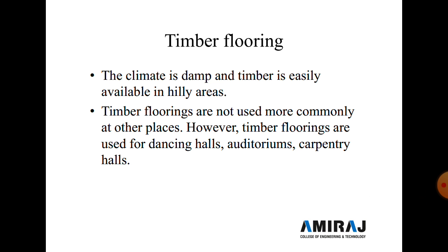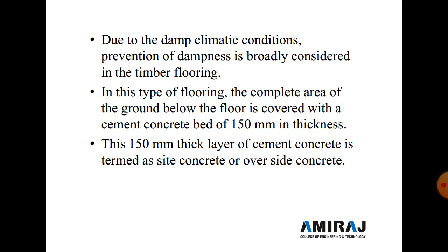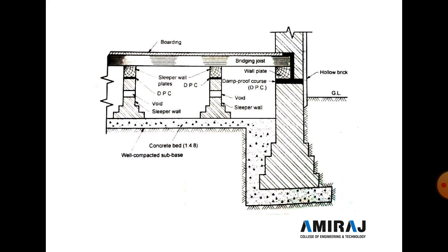auditoriums and carpentry halls. So here, due to the damp climate condition, prevention of dampness is broadly considered in timber flooring. So in this type of flooring, the complete area of the ground below the floor is covered with a cement concrete bed of 150 mm thick layer, and this 150 mm thick layer of cement concrete is termed as site concrete or overside construction. So in this figure you can see here